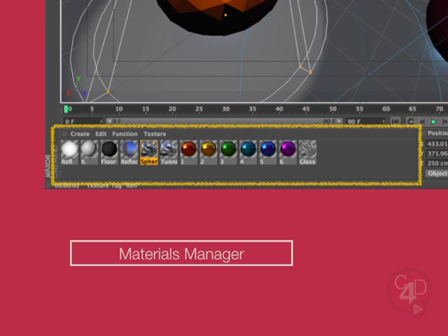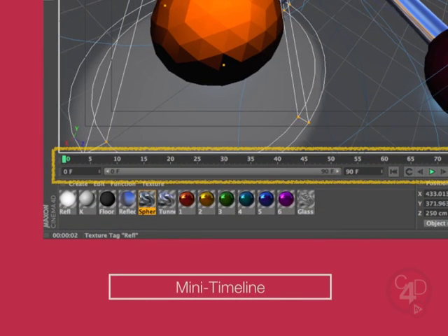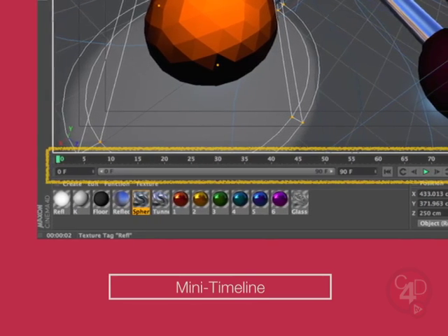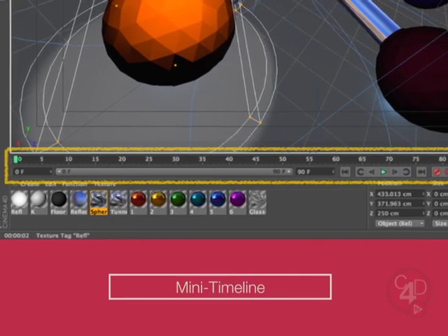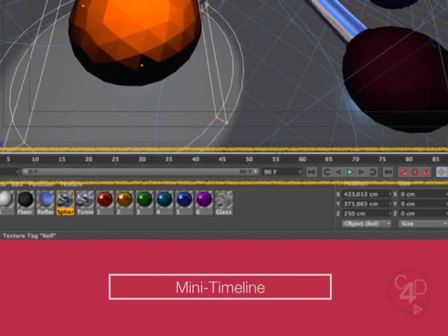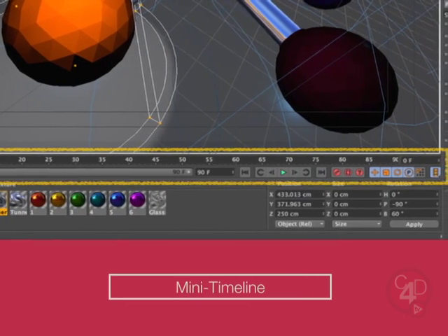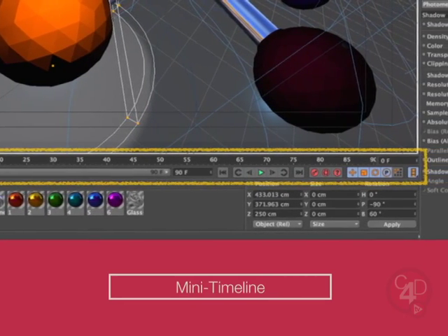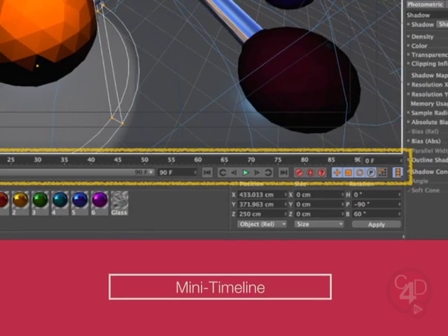in the Object Manager. The Mini Timeline is a simple yet powerful section of the interface that displays instant feedback during the creation and editing of keyframes. With easy-to-use playback controls, project duration parameters, selective animation options, and plenty of shortcut commands to help you do most of the keyframe adjustments without visiting the more complex editing timeline window.